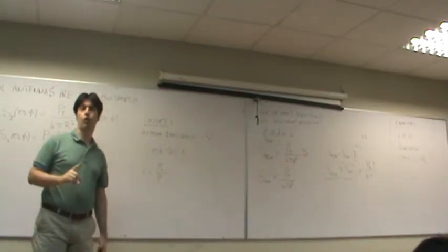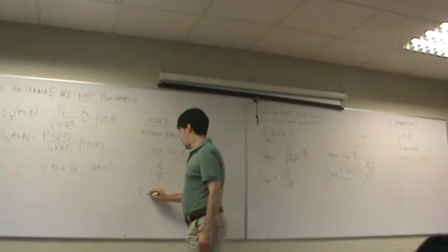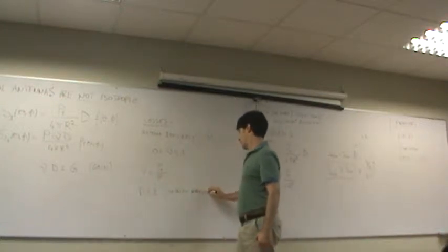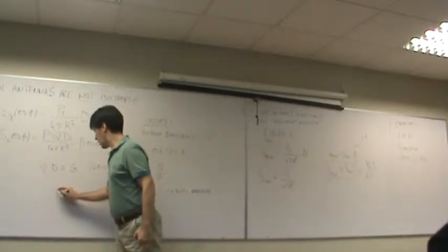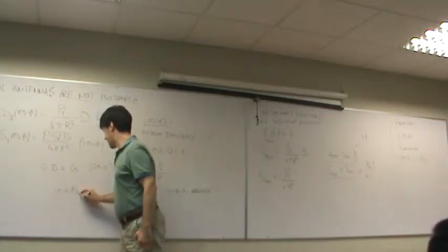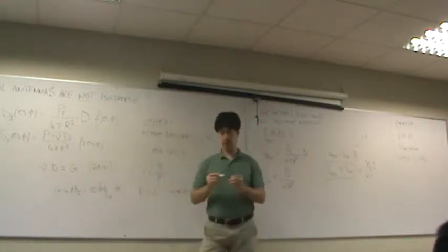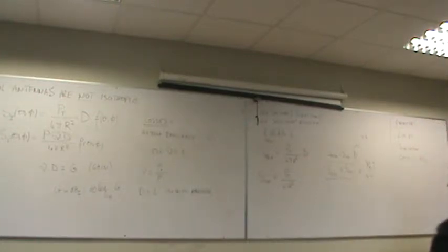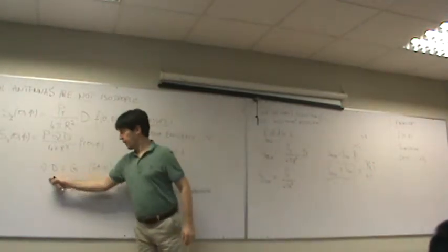And since D is equal to 1 for the isotropic radiator, the gain in dBi is simply 10 logarithm base 10 of G. And this is a parameter that is more important than the directivity itself, because it takes into account the efficiency of the antenna.